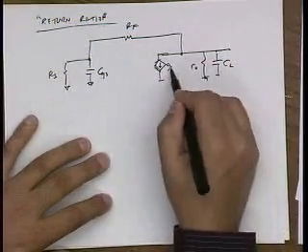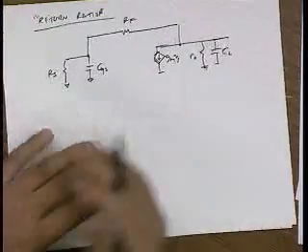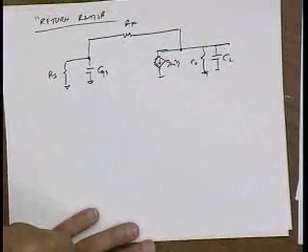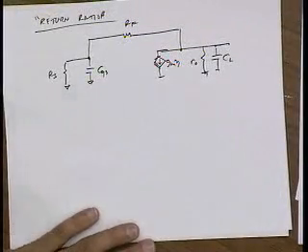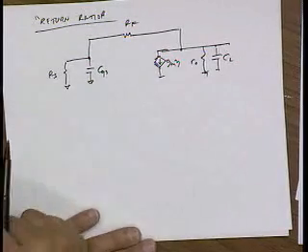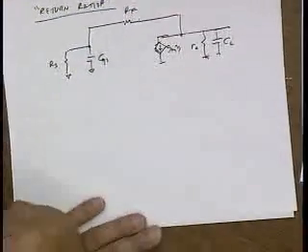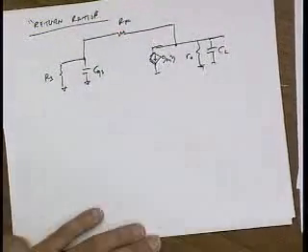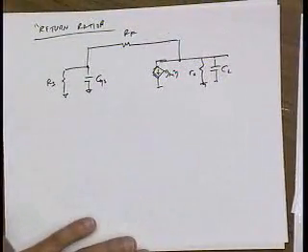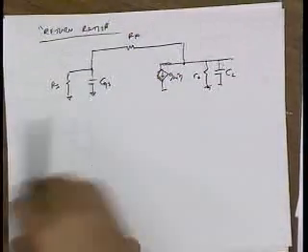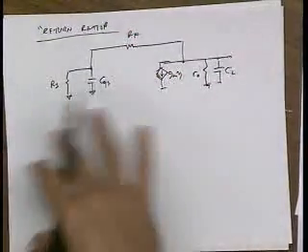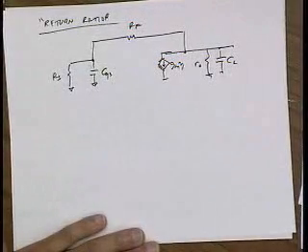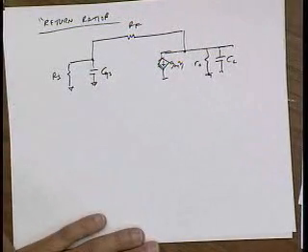And the idea is that this is a loop gain, right? By definition, it's the gain you experience as you go around the loop. And so if I break my loop, inject the signal, and look to see what comes back at the point where I broke the loop, that's the loop gain, right? And no matter what your amplifier looks like, no matter what the feed forward is, no matter what's going on, the actual loop gain should be easy to compute, right?